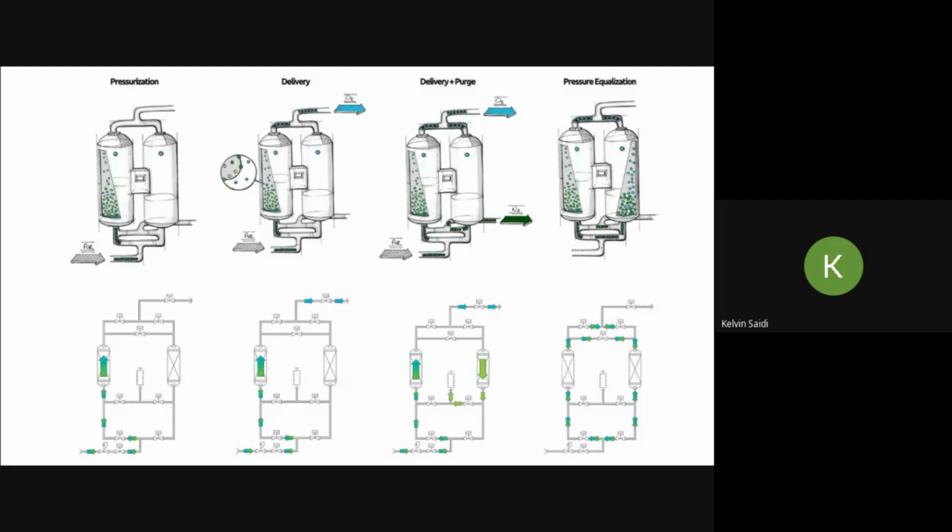Depending on the type of oxygen concentrator, different methods are used to accomplish the purging process. Some concentrator models, including the ASEP and InvaCare models, use what we call an equalization valve, while models like the DeVilbiss 525 and 515 use an orifice.